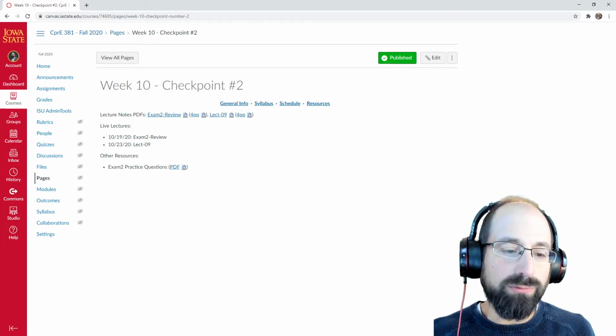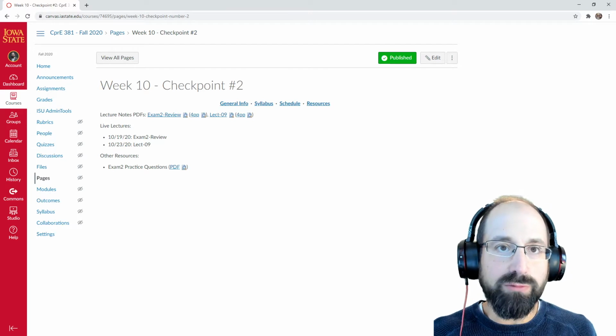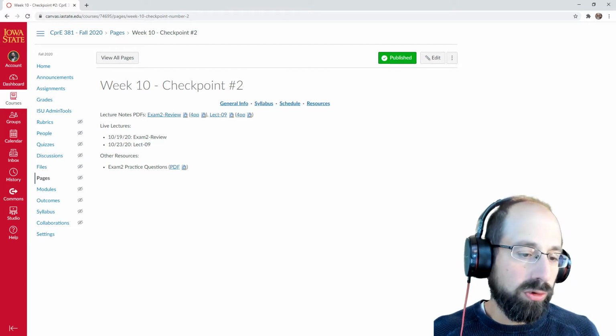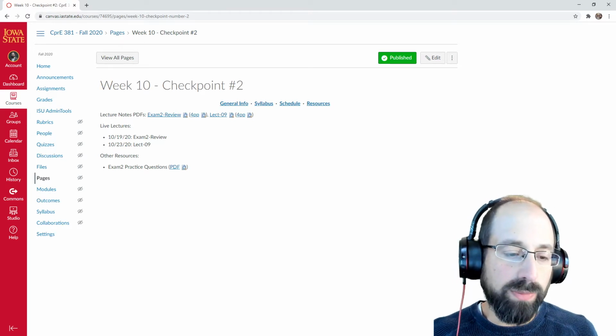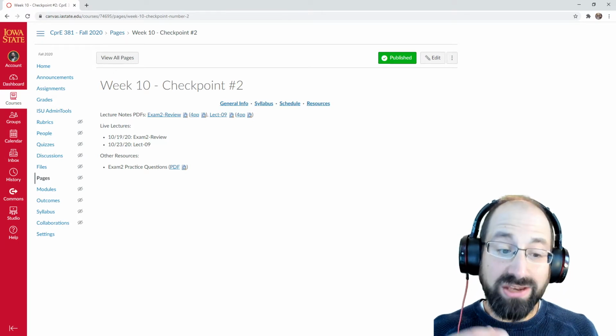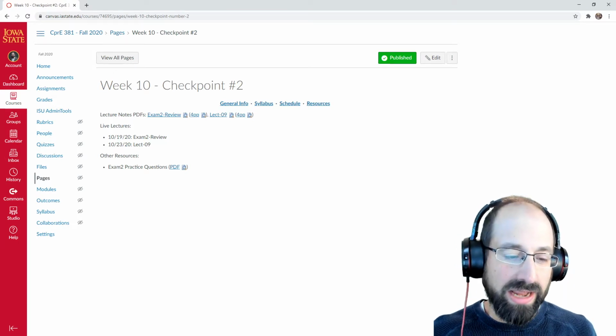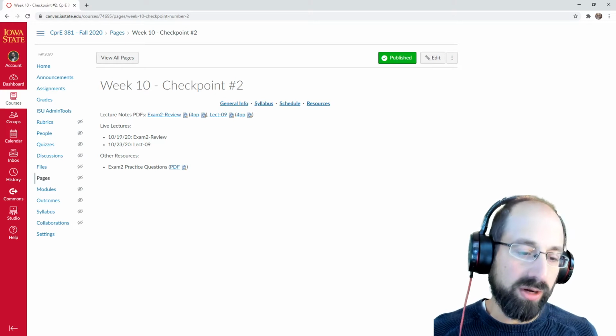Where life would have gotten really complicated for Project B is if we were wanting to support the store byte and store half word and load byte and load half word instructions. Then you'd really have to very carefully think about how we actually store the right values into our memory. We could have done it. It would have been an extra couple of weeks.